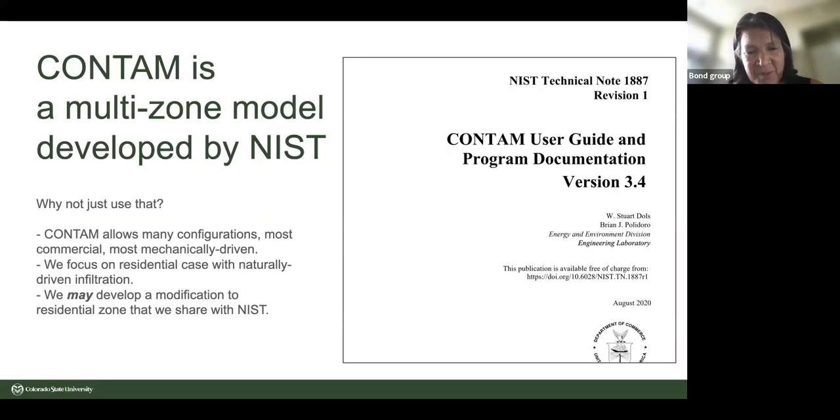Oh, okay. One of my slides disappeared. That's why we went straight to the NIST slide. So one of the benefits provided by what's called infiltration models, and so you may hear of a model we refer to as the LBNL model. There's another one called the AIM model. These are simple one zone models that try to do that balancing, determine how much flow is in or out depending on the conditions, and then determine the magnitude of the flow. And so they're kind of the in between.